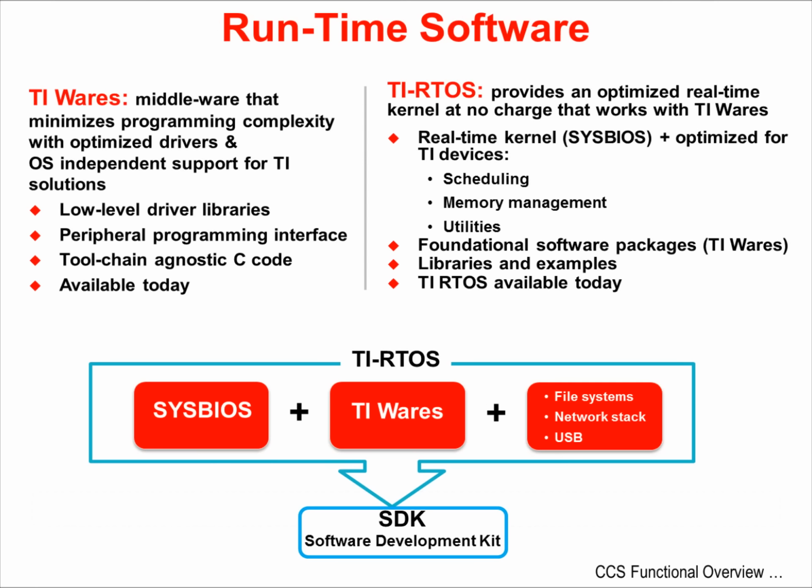TI's runtime software support includes TI-Wares and TI-RTOS. TI-Wares like TivaWare minimize programming complexity with low-level driver libraries and peripheral driver libraries. They can be used with multiple development environments. TI's RTOS is comprised of an optimized real-time kernel called SYS/BIOS. SYS/BIOS is optimized for TI devices and includes scheduling, memory management, instrumentation, and is fully compatible with TivaWare. Programming of USB and Ethernet ports is made easier with file systems and stacks.